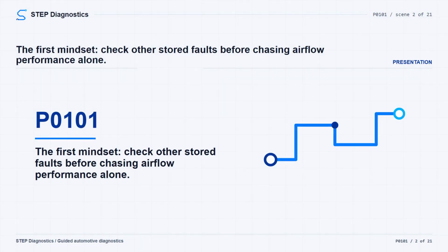The possible fault areas can include the MAF sensing element, its ignition, ground, or signal circuits, intake or charge air leaks and restrictions, EGR leakage, skewed pressure or temperature inputs, or PCV-related air leaks. Start with the basic system checks, follow a structured diagnostic approach, and if other codes are present, check what they mean first, instead of chasing P0101 in isolation.